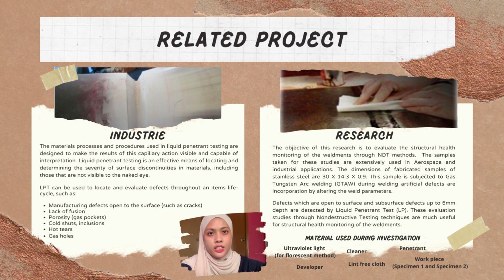LPT is one of the most widely used non-destructive testing methods. LPT is based on capillarity, or capillary action, where a liquid is able to flow into narrow spaces without the assistance of, or even in opposition to, external force such as gravity.